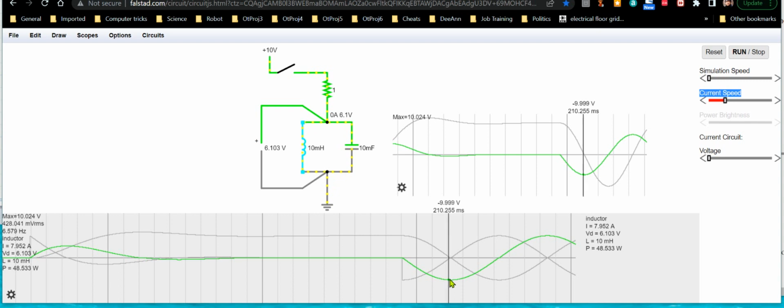But right here, this voltage you see is the actual voltage technically across the capacitor, but also across the inductor too. Because remember what I said: when an inductor is discharging, it will generate whatever voltage it takes to try to keep that current from falling further. Whereas the capacitor is eating up that energy, but its voltage is increasing. So what does the inductor have to do to maintain that?